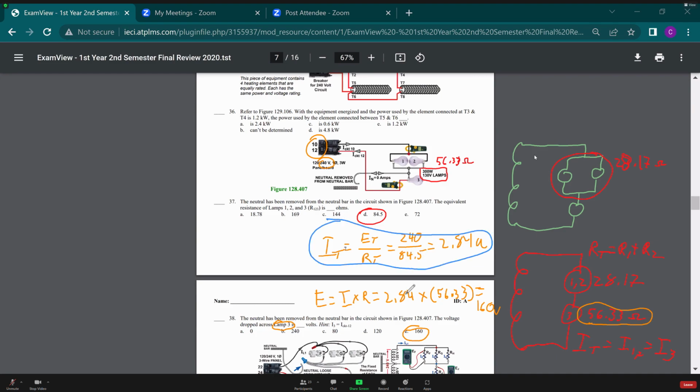So you had to find this portion, this current total, to figure out what that voltage through 1 is, because that current total is the same throughout everything. And we need to find one number that we can answer the entire question off of. We got to compare apples to apples kind of a thing. That's why we had to find current total and then use the resistance of 1 to figure out the specific voltage of the lamp.